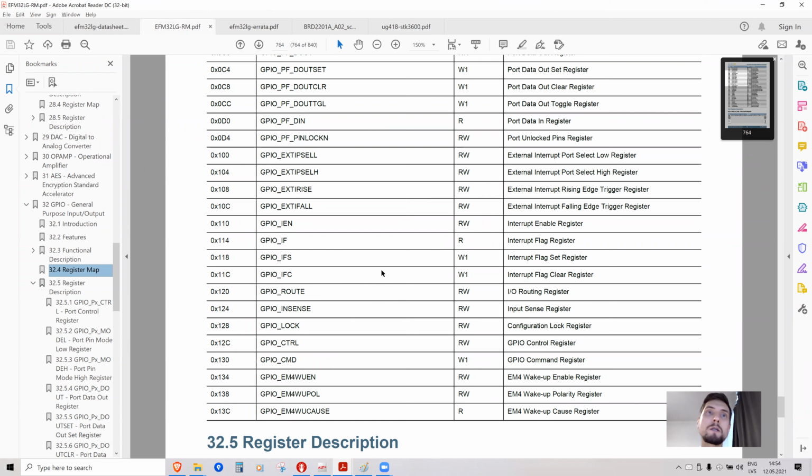And the second is the pin itself can have a pin number interrupt, and you can understand which port, which pin it was. Just two pins, for example, in these microcontrollers cannot have the same number. So if you use port B pin 9, you cannot also use port A pin 9 for interrupts, because then microcontroller doesn't know which one it was.